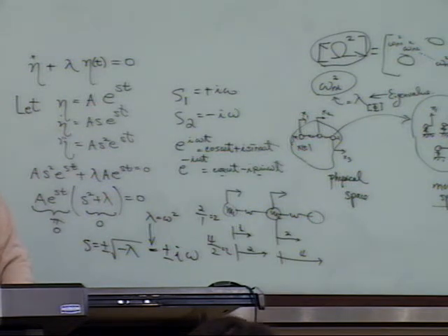And so if phi r is a solution, then alpha r, some constant, any constant, times phi r is also a solution. This implies that the mode shape is unique, not the amplitude. Make sense? That's what the mode shape is.